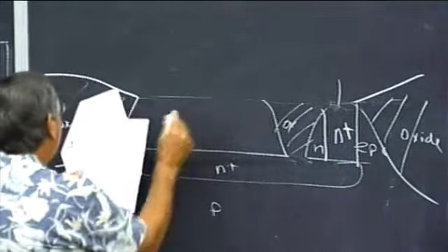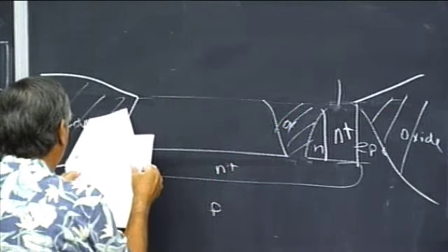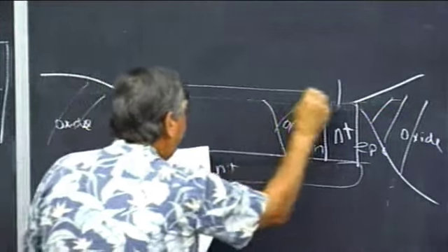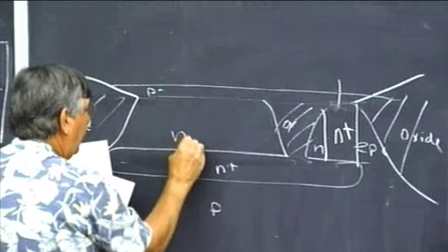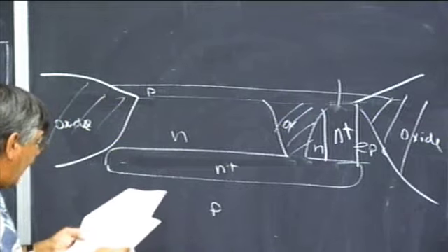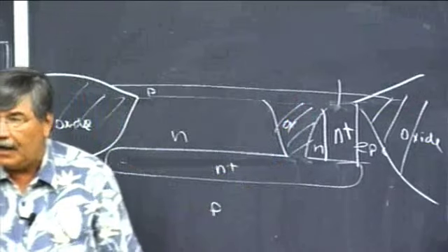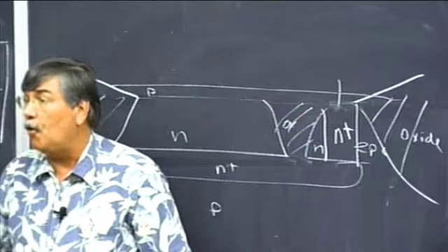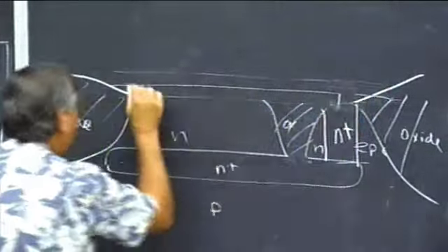And then we get to the good part, and I may have to blow this up a little bit so that you can see, but this is where the really good stuff happens. First, I'm going to implant a shallow base layer. So this is going to be P moderate doping. This is kind of in between P-type doping, and that's going to form our base. And the best part happens right now. I'm going to deposit polycrystalline silicon. I'm going to include heavy, I think it's arsenic doping, so it's going to be N+. So I'm going to first put an N+ poly layer.